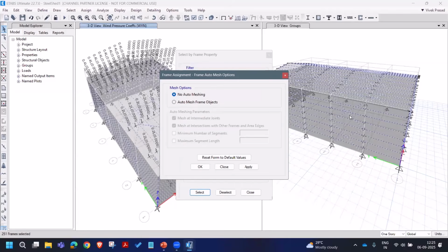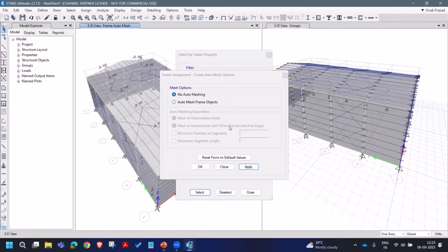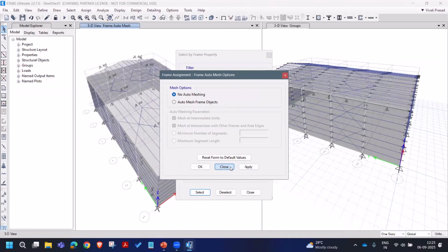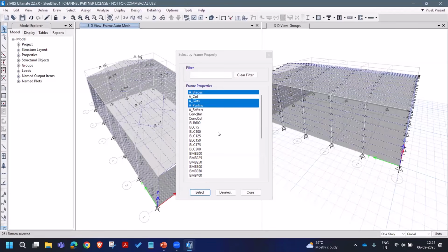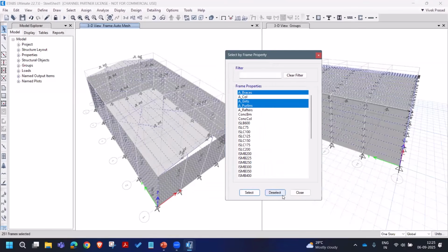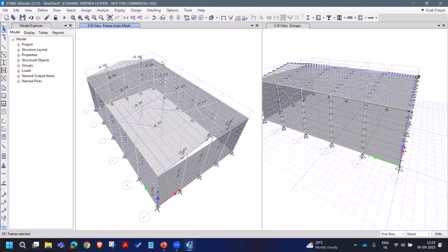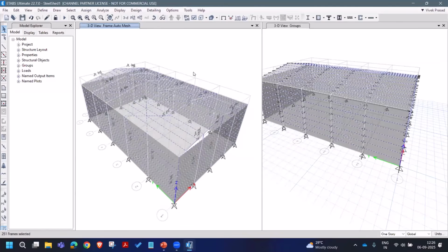I'm assuming the bracings are not connected at the center point at the crossings. So we were using this for that purpose. Right. And then we'll select all of these members. You can assign the unbraced length ratios. We can see that once and then we can overwrite it. So I'm skipping this for now.